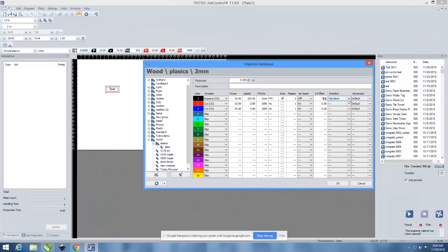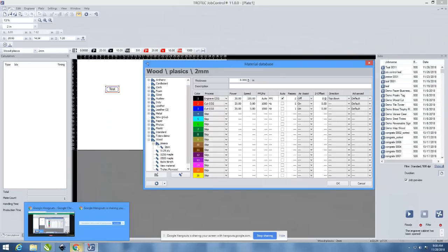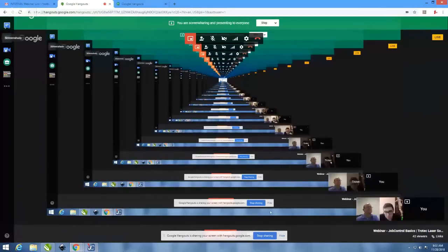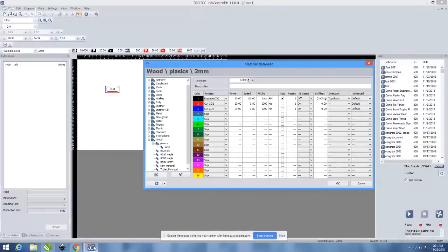But if you want to have a clear engraving, for example, if you're doing a trophy or a plaque, and you're reverse engraving on the back of the acrylic, and you want to put Rub 'n Buff or acrylic paint on the back, if you're engraving that in focus, you won't see the paint on the other side. You want to have a clear engraving so you'll take it out of focus.